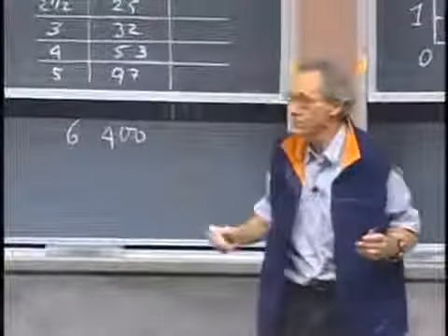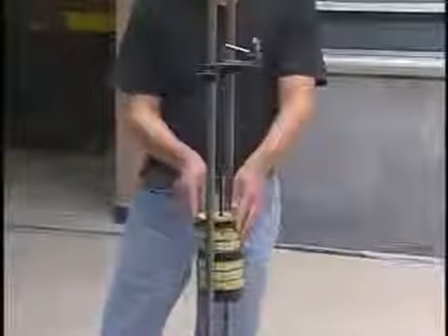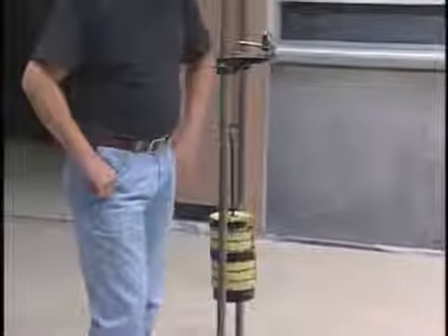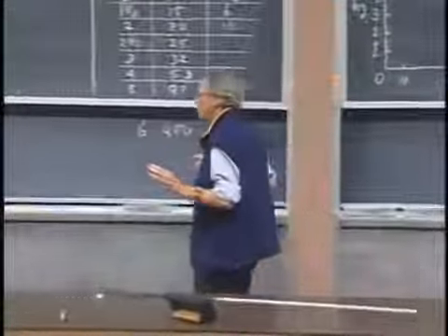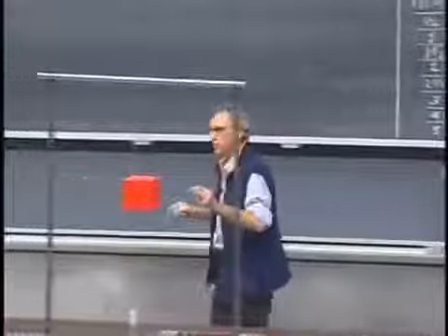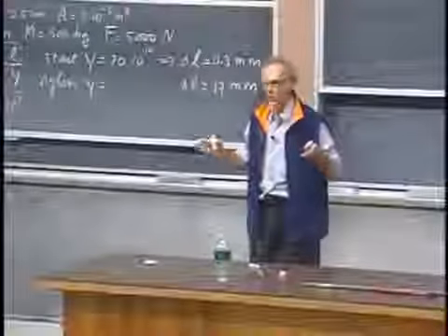Put on 7. It will go through the ceiling now, so we lose it. But what I want to do now is get to the breaking point. We can no longer measure the displacement, but we are very close to the breaking point now. So we're going to load it up to the point that it will break, and that allows us to measure the ultimate tensile strength.